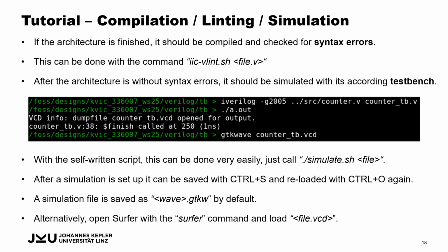And of course, we have to simulate the architecture. So when there are no syntax errors and warnings, we can simulate this with an additional Verilog test bench. And normally you would have to enter the following commands. So we use Icarus Verilog, and then in the Verilog counter test bench we dumped the .vcd file, and we can then open this in GTKWave or in Surfer.